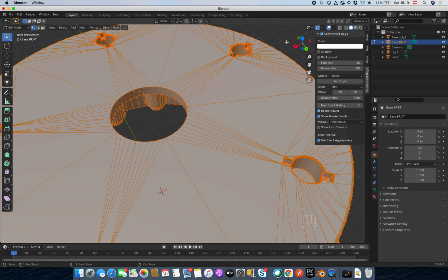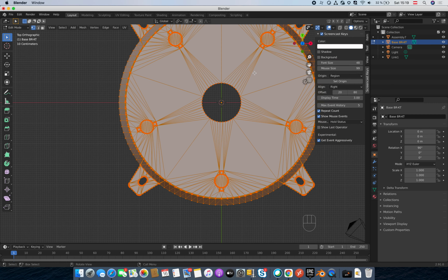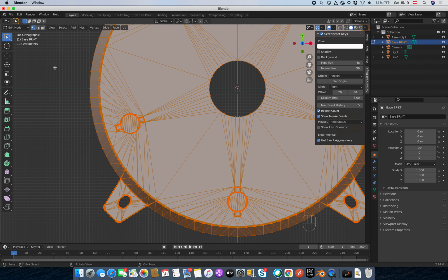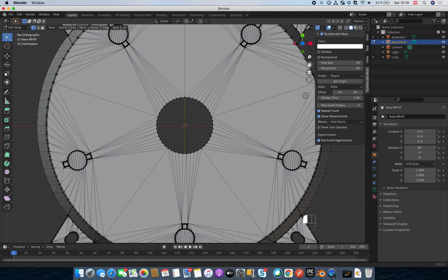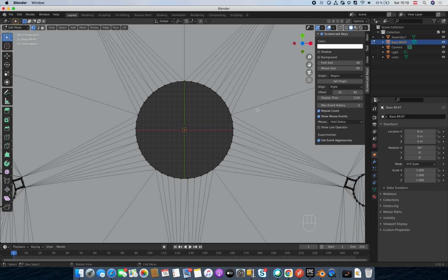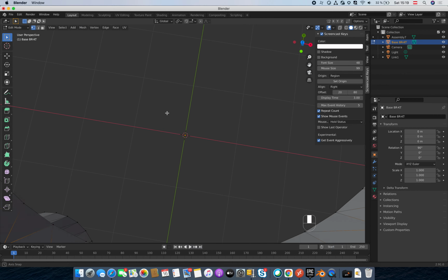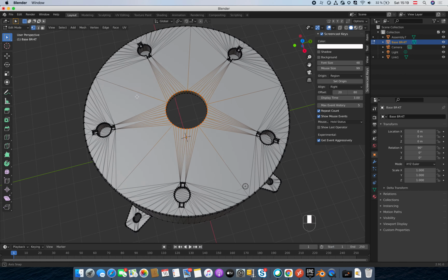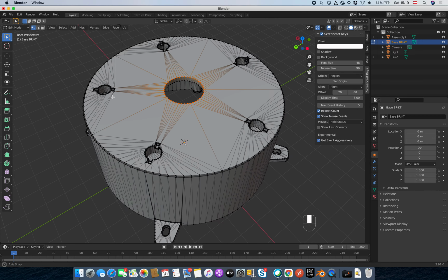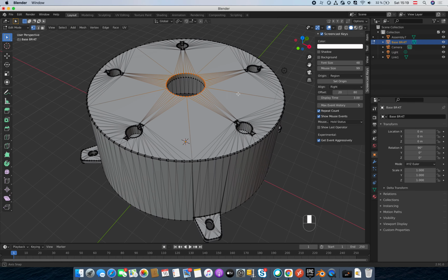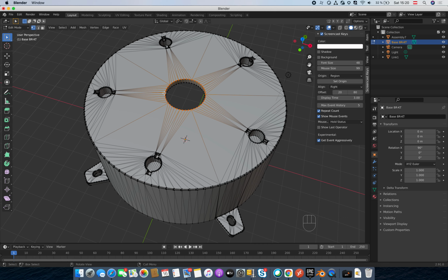So let's click over the axis and click somewhere away, and yeah, let's use the box selection, and I want to select these vertices basically that belong, as I said, to the upper circle. I just want to make sure that I didn't select any other vertices. No, I didn't. Good. So what I want to do now is to bring that 3D cursor to the center